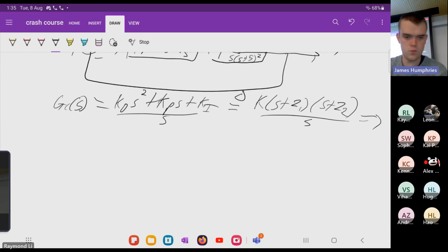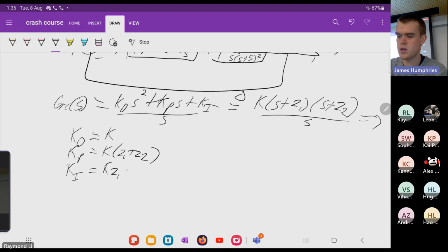Yes, hopefully. Cool. So therefore KD is equal to K, KP is equal to K times Z1 plus Z2, and KI is equal to K Z1 Z2.